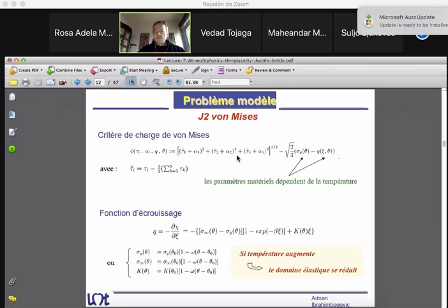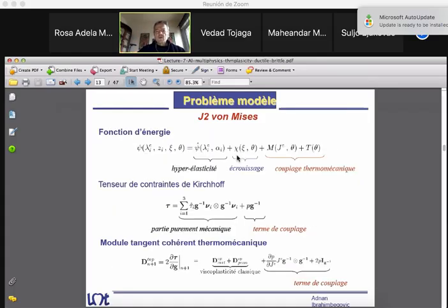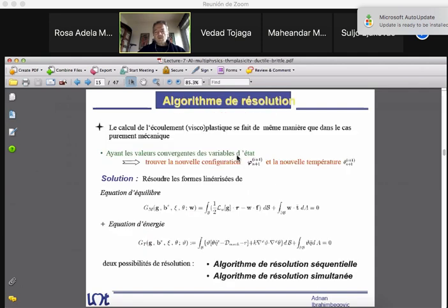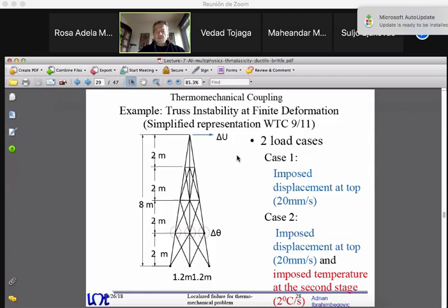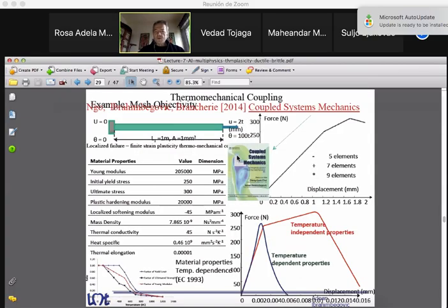We took all this to be linearly reduced. That means when temperature goes above the reference value, you reduce the yield stress and you reduce the saturation stress, and everything was done linearly. What we are doing here is a little bit more realistic, whatever that means, because it's set in the Eurocodes, and I don't know who developed this, but anyway, we trusted Eurocodes, because it was just an illustrated approach. It was not really done for any client who was paying a lot of money.